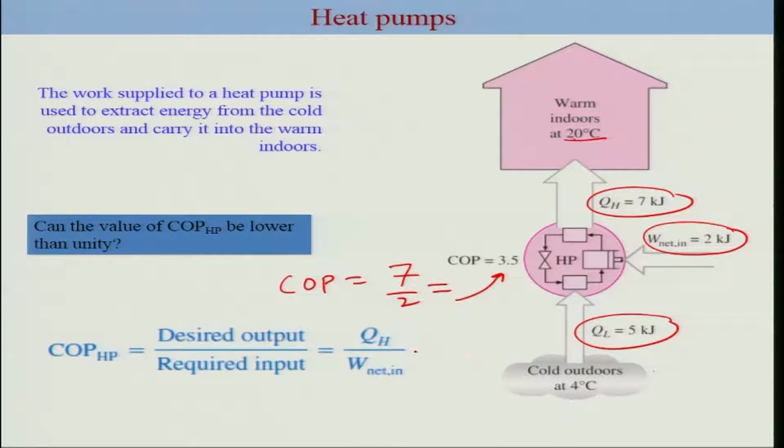So the question is, can the value of COP be lower than unity? This is possible if you have a lot of heat losses through pipes and other devices which are part of this heat pump. So in practice it can be possible.